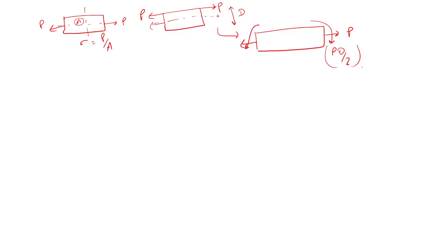And stress due to moment, what would be the bending stress? Sir, it will be 6P upon BD. My by I, right? You are telling the answer, but this is My by I. So you can get the moment, and y is the distance from the neutral axis.